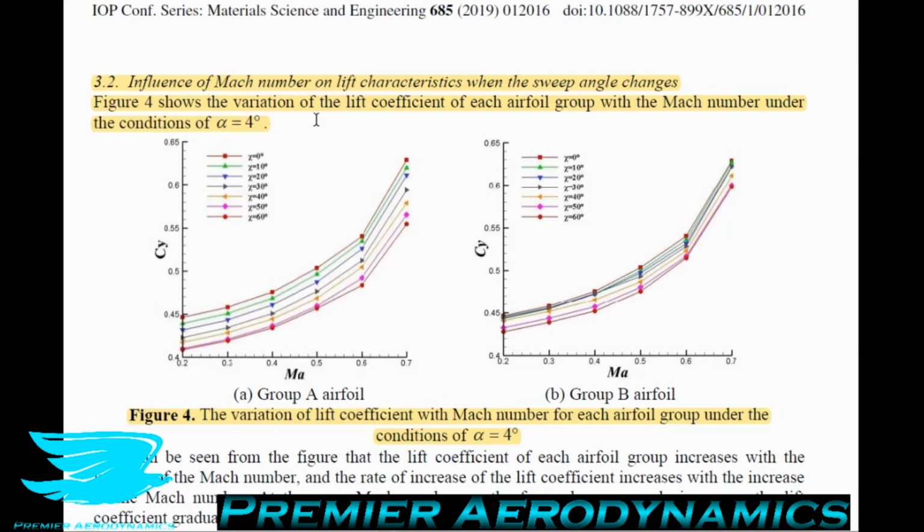And what this means is that a thicker airfoil would have a lower critical Mach number. Let's say you have a free stream velocity of 0.9 Mach number, you can have a critical Mach number at that point, which means you're getting sonic flow there, compared to a very thin airfoil, which may still be completely subsonic. So the greater the thickness of the airfoil, the lower the critical Mach number is. This is why it is important for this particular application.